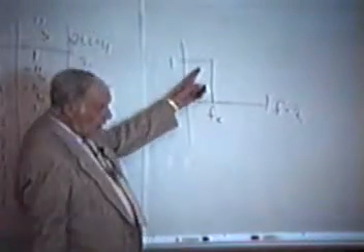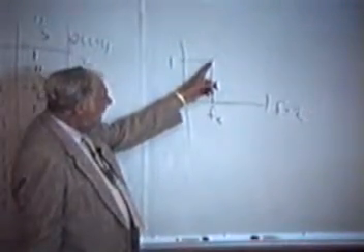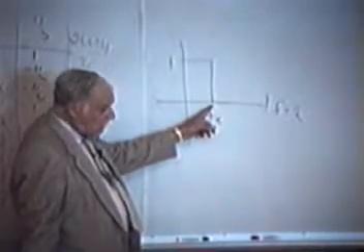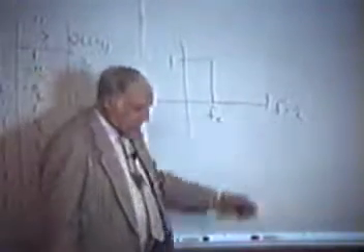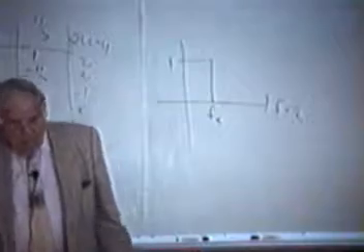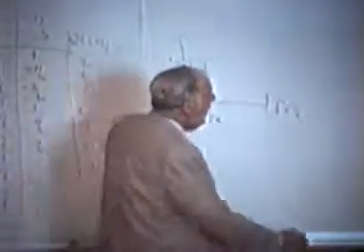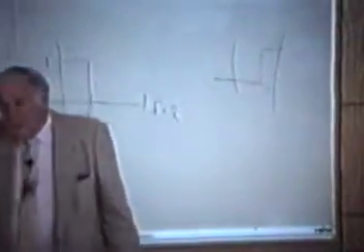I usually want, this is a low pass filter, I want to pass one out to here. At a cutoff frequency, I want to stop passing, I want to cut those off. That's a low pass filter. I might want a high pass filter. I might want to cut out all the low frequency and pass only high frequency.